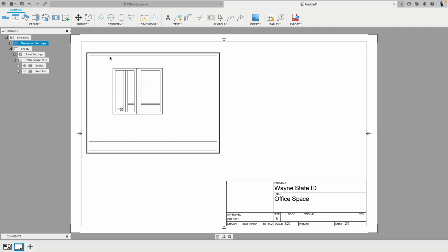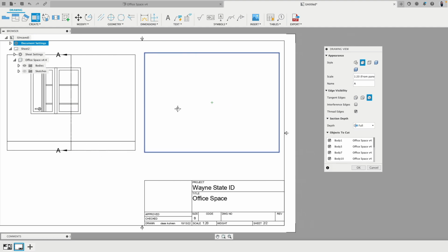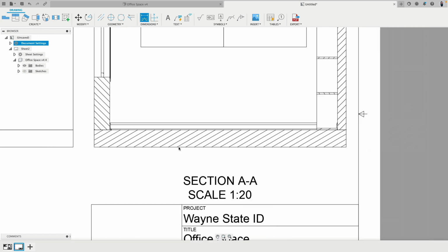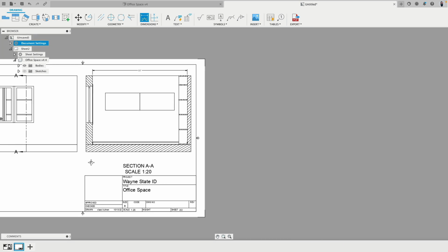Okay, very good. And what I'm going to do now is here is a section view, and create a section from maybe this midpoint down to the midpoint at the bottom. Click OK. Move this to the side. And there. Now we can look actually into the space through there. Also here, we can easily add dimensions to everything. 11 feet. That's the way how it should be. Interesting. This is angled. I have to check this, why this shouldn't be. Anyway,